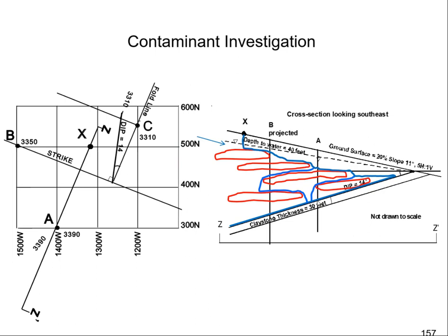Borehole A is here and we don't know much about it. When I first put this question together, I was thinking, okay, so it's probably seeping out here at the ground surface, traveling overland, which would be what, 33, 35 feet, the hypotenuse on a triangle here. And then it would be entering down below the claystone, intersecting the ground surface. And that was, to me, the most logical answer, given the information that I had. But that was not an answer choice.